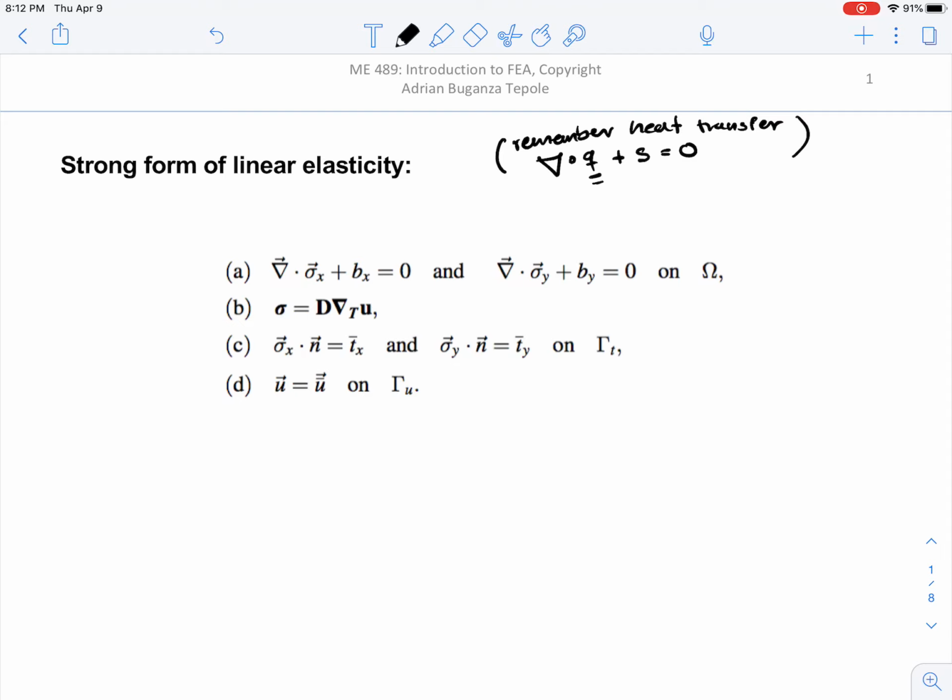And there's a constitutive relation also, if you remember the way we had defined this flux of Q. In this case, we are going to have sigma x and sigma y, these sort of linear momentum fluxes, you can put them in this matrix, which is the stress matrix, and you can relate that to the gradient of the displacement.